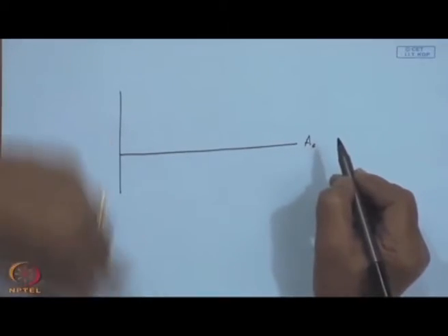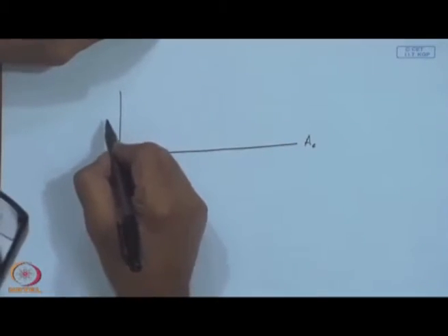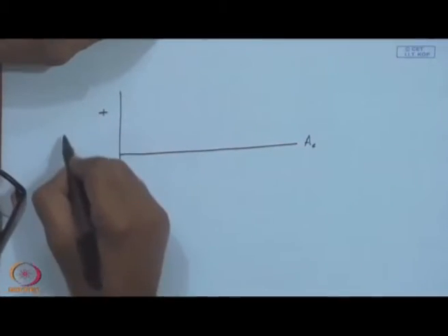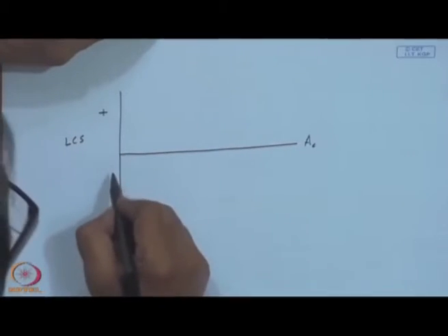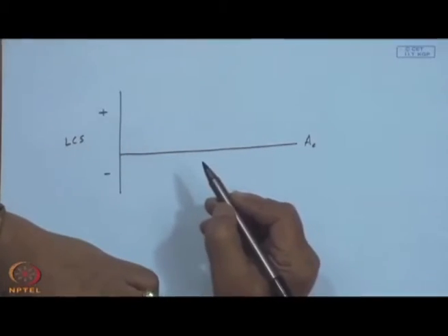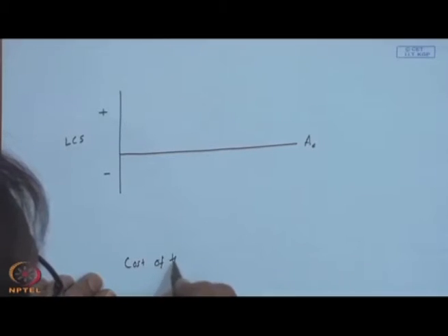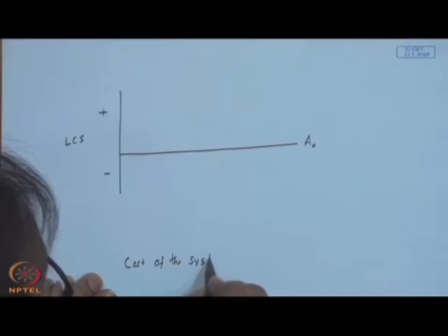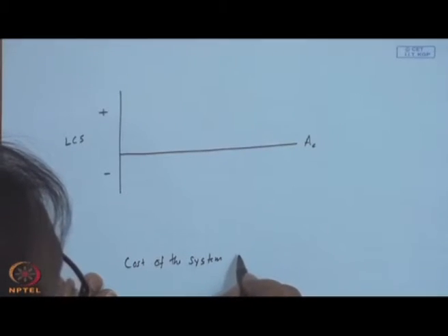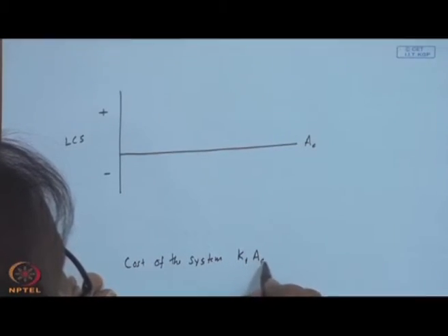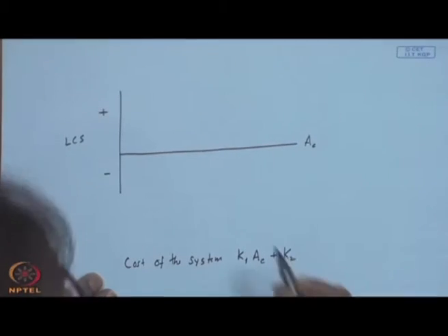the area of the collector is the main parameter, the other things are fixed. We are examining a given system, that means the location is fixed, application is fixed, the load is fixed, everything, and operating parameters. Somebody through simulations came out with the best orientation, slope, flow rate, etc. We can always divide the total cost of the system as a constant K1 times the area of the collector plus K2.